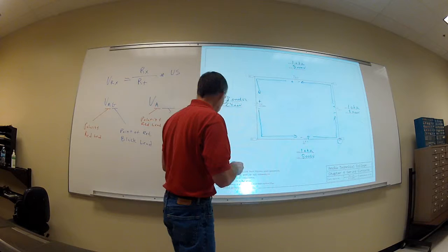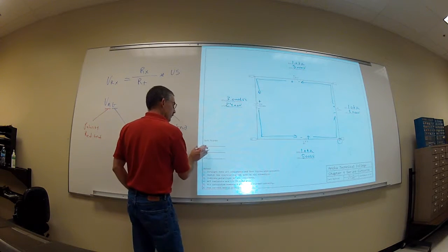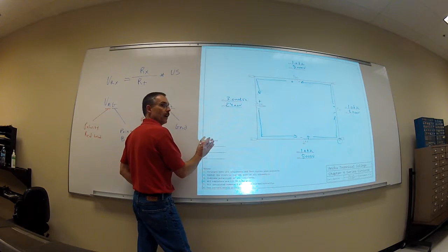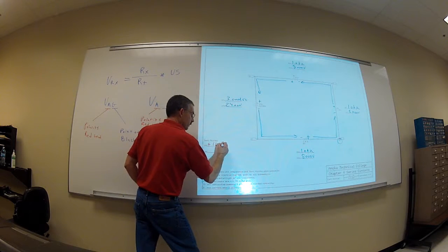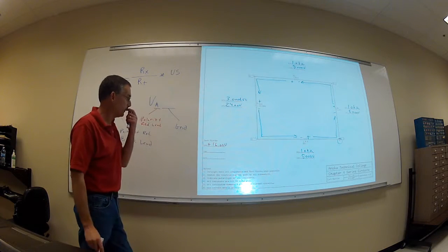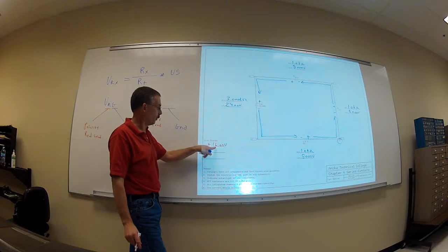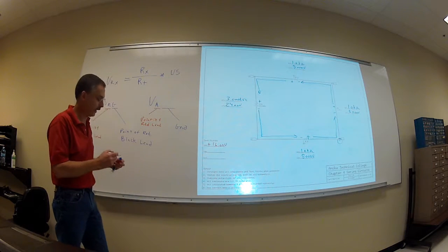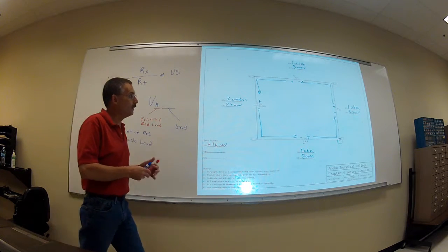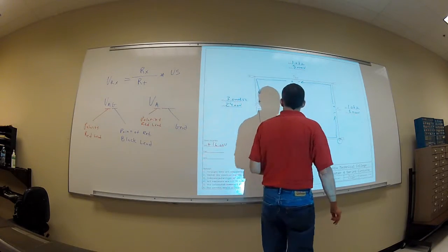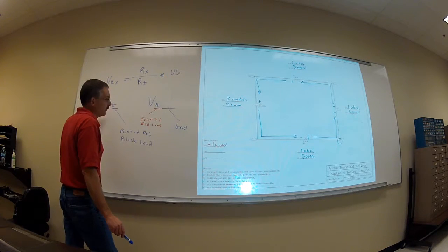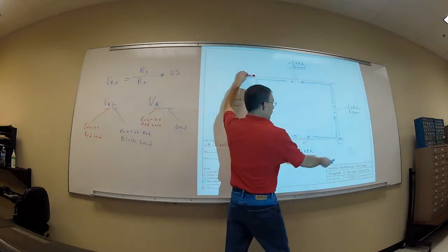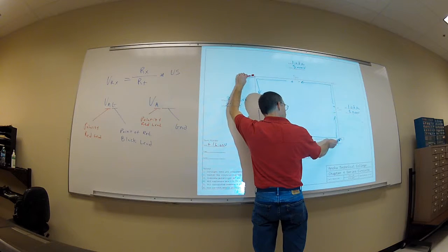16 volts. And what did I say always about test points? What do they mean? Polarity. So we know that my polarity across this one is positive 16 volts. Okay? So make sure you get your polarity in there, digits, and your units. It doesn't matter which way you go, just as long as you follow your current path. So, again, test point A, my red lead's going to go on test point A, black lead's going to go on G, black lead never moves.